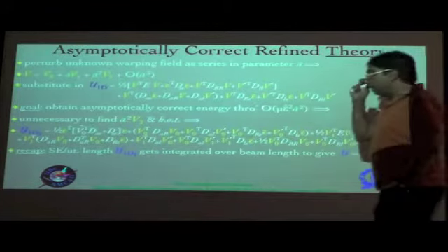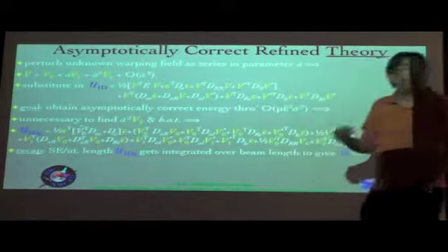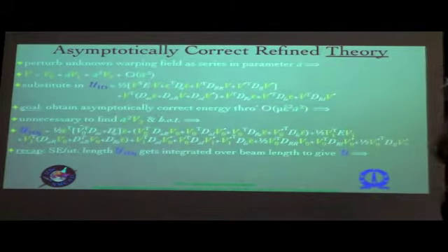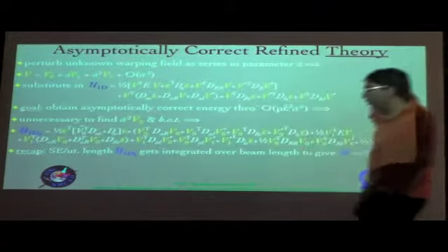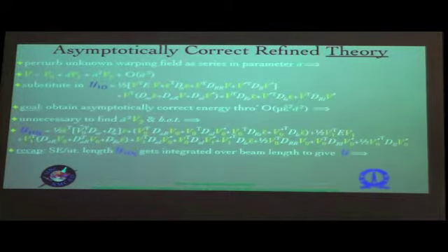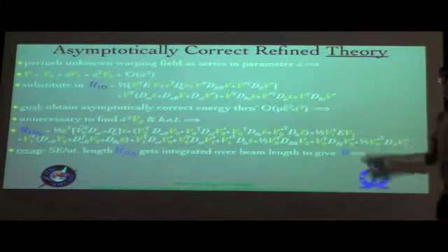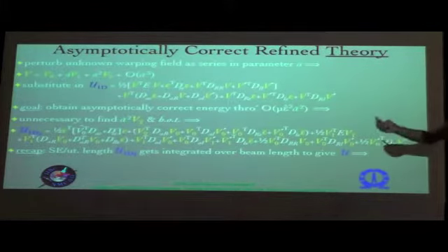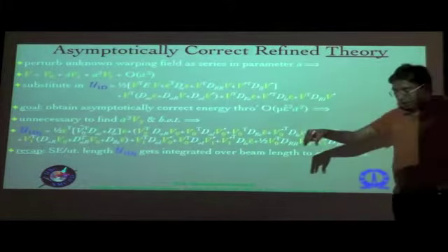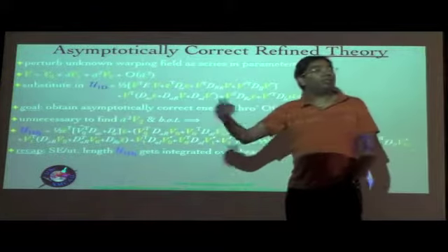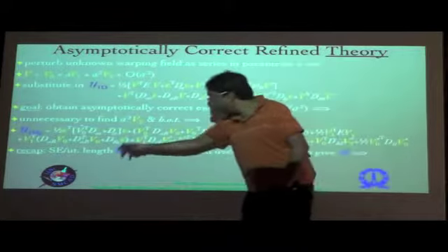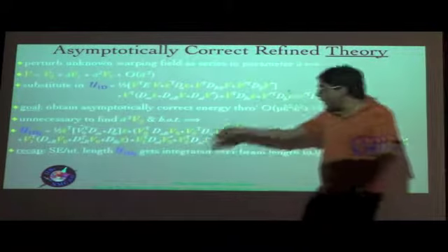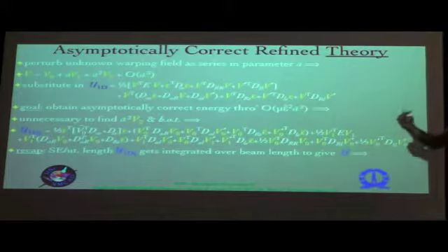Now you recollect that the strain energy per unit length, at this level, that is the first order approximation, and therefore given the subscript Roman 1, gets integrated over the beam length to give U, right? So you have two levels of integration. You had the three-dimensional strain energy density, energy per unit volume. You integrated that over the cross section, you got this, and eventually this has to be integrated over the length to give the total strain energy of the beam as a whole, right?